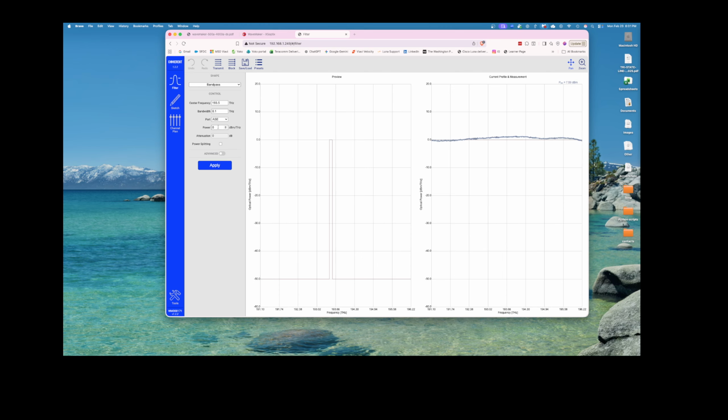And I have some power control. This is the EDFA that we have some control over, so I can make the power a little higher. Oh, I made a mistake there because I had a filter already put in here, but you can see what's going on. So if I make the filter go back down to 0, basically all this is doing is feeding the ASE through the filter, and that's it.